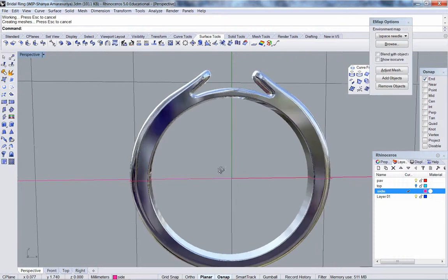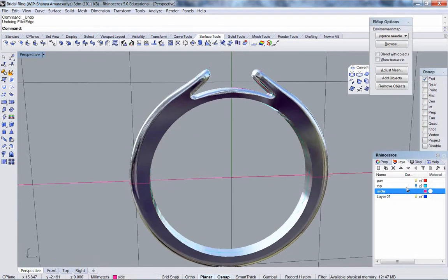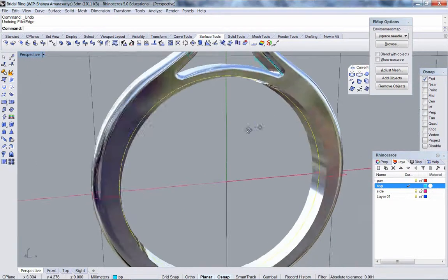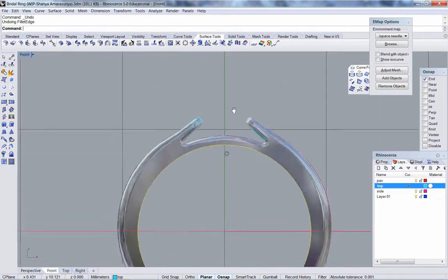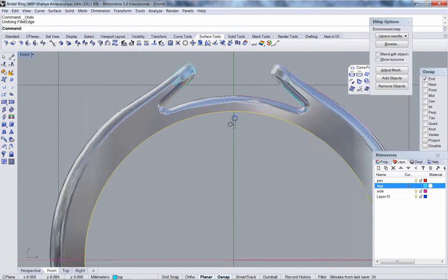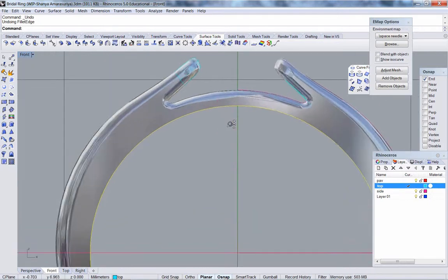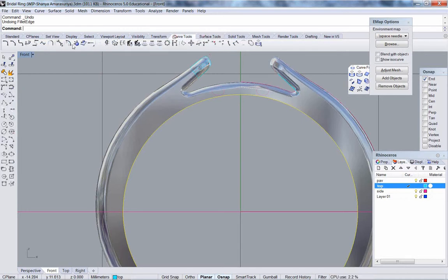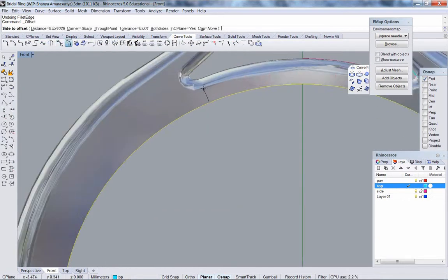Okay. To do the dome, would you just create another ring inside? Yeah. But you have to expand this so that it can accommodate. Yep. I would take this and offset it. I want to make sure that I don't bite into this fillet work that I've done here.